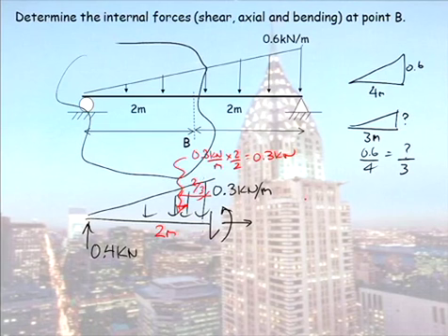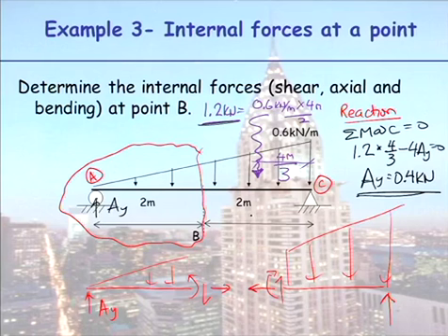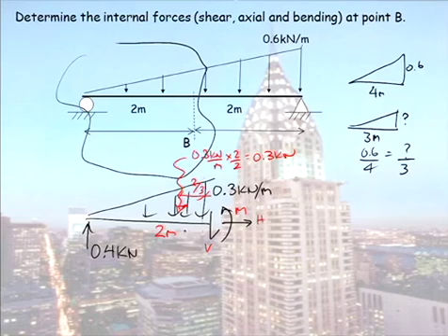Can you see? I'm not doing anything different. So now, I have all my forces noted, all my reactions noted, my 3 unknowns this time. When I calculated the reactions back here, hopefully you can all appreciate there was no horizontal load applied here. So our AX reaction here was equal to 0. So in that case, my 3 unknowns were forces. In this instance, my 3 unknowns are a horizontal, vertical, and a moment.